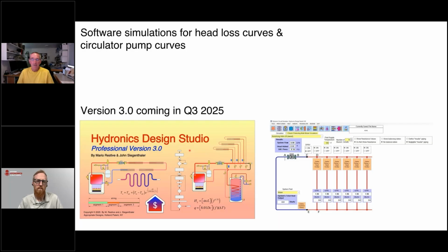How will I pick it? I'll give you a couple examples. Radiant floor heating in a residential application where you're likely to have people walking around barefooted or in socks, I would suggest nothing more than a 15-degree temperature drop at design load. And if it's a high-end project, I'd probably say 10-degree Fahrenheit temperature drop. Why do I pick those numbers? Because I don't want somebody to say, how come the floor is noticeably warmer over here versus somewhere else in the same room? The larger the temperature drop, the more noticeable that variation in floor surface temperature is going to be.